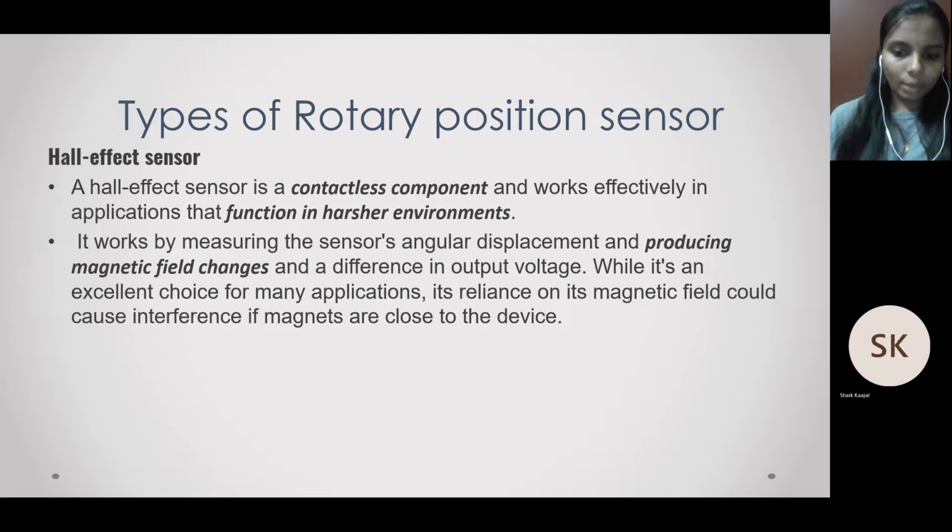The Hall effect sensor provides three overlapping signals phase shifted by either 60 degrees or 120 degrees, thereby making the speed information available by capturing the time intervals between two phases. Further, the algorithm of the controller is utilized to numerically ascertain the position, as required for sharp firing of MOSFETs.